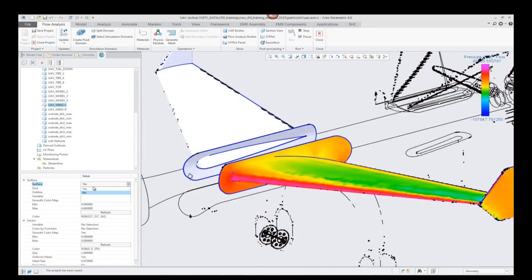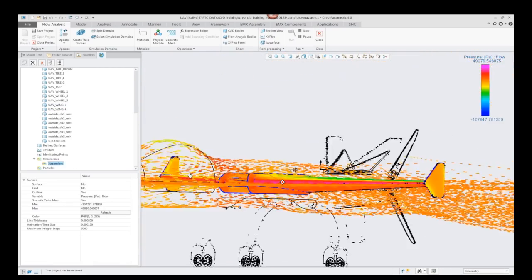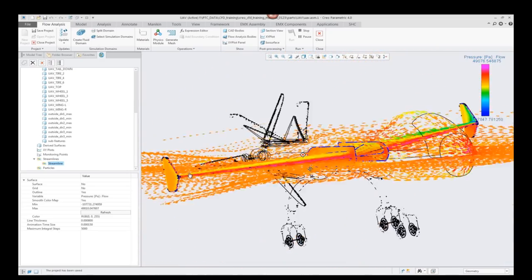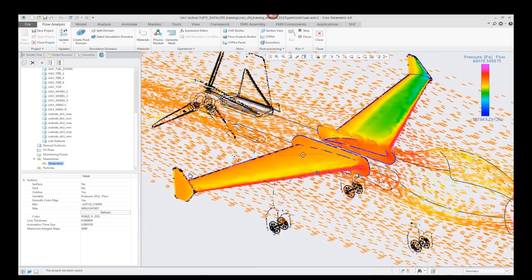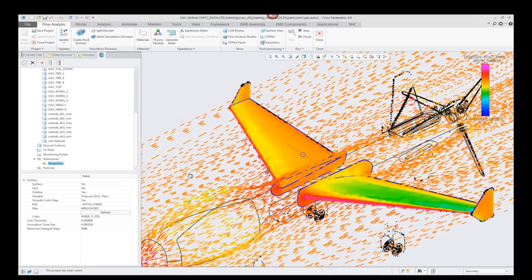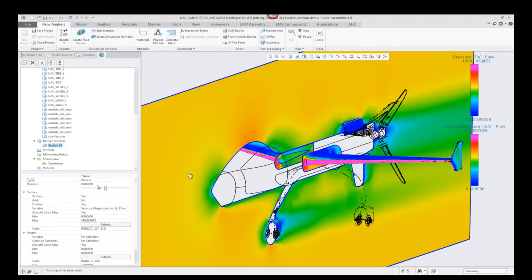Let's go and compare and contrast now with the wing on the opposite side of the plane, and let's go and put the pressure profile on for that. And what you'll notice is, because this wing here has not been bent around the camber line, you can see that we get the same pressure on both faces. Well, we don't actually have compression and suction faces since it is symmetrical, so we're getting the same values on the top and bottom faces of the wing as we see it.